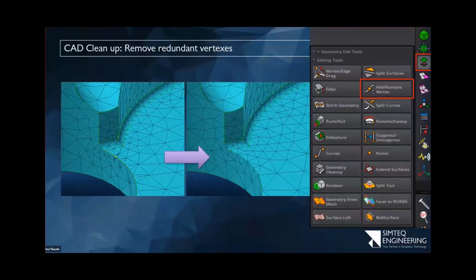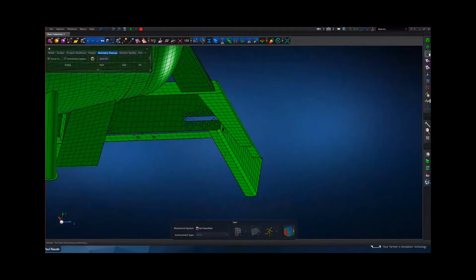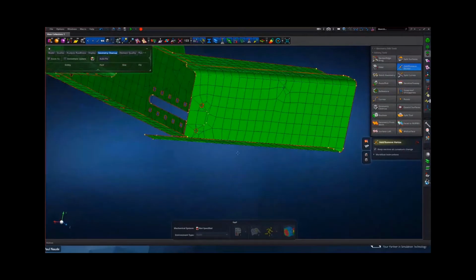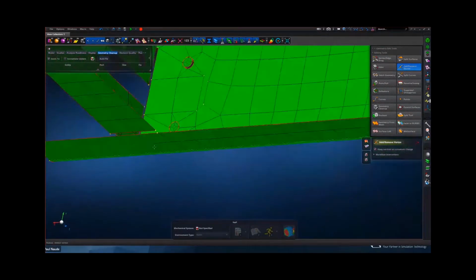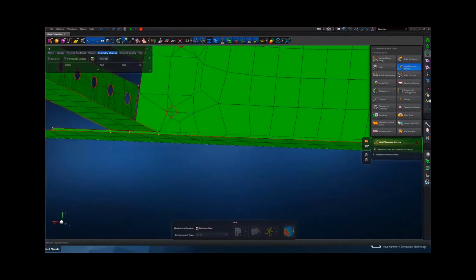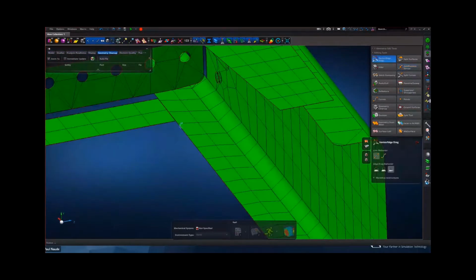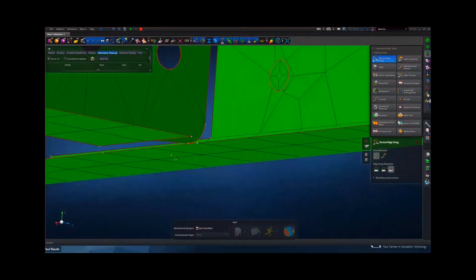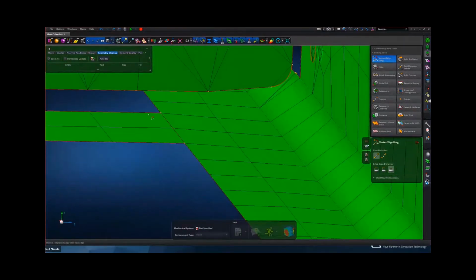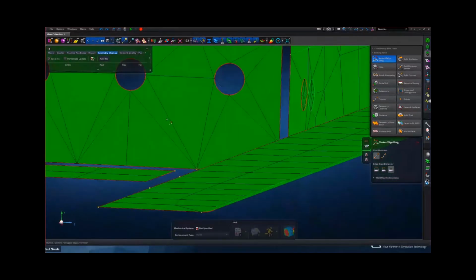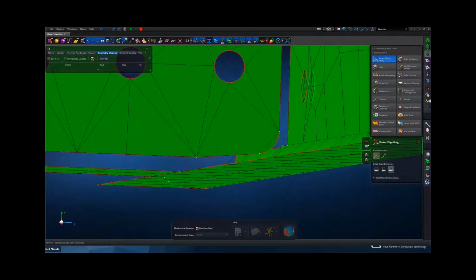The next tool that I want to showcase is the adding or removal of vertices. Normally we simply use this to divide an edge, for instance. If I want to divide this edge so that I can match this mid-surface to this one, adding vertices is a useful way to divide this edge so that I have a shorter section that I can simply snap this one to. And you see it has now actually even moved that plate out of plane a bit to do this match.